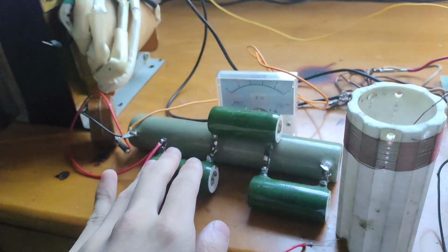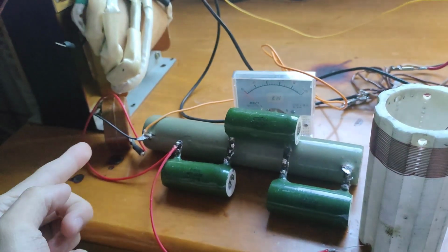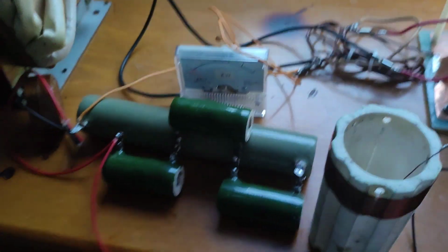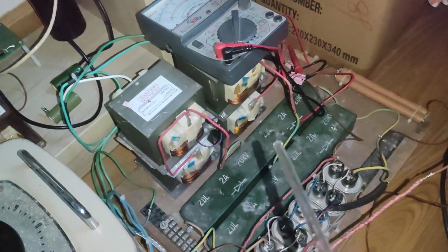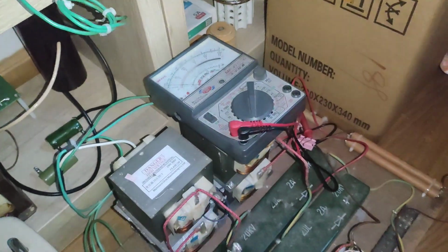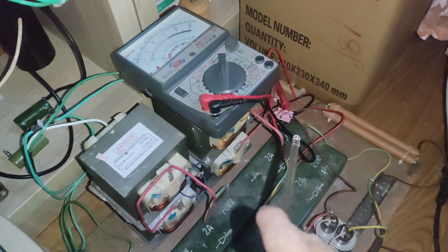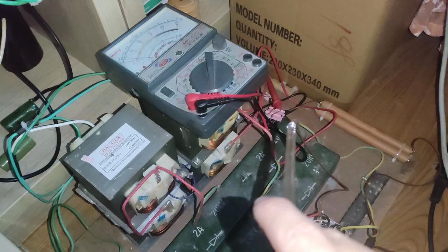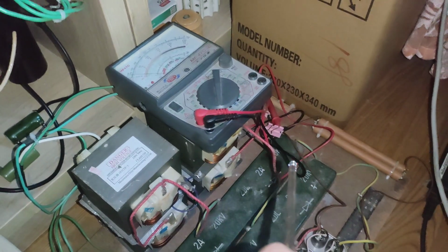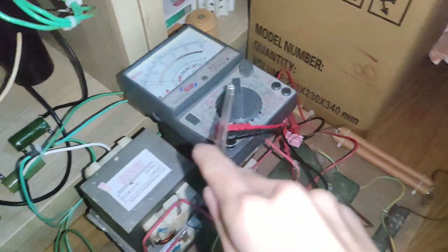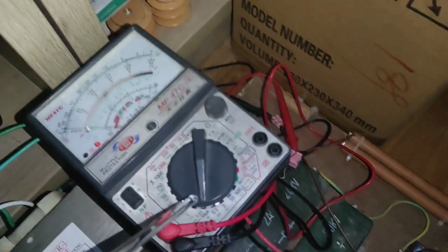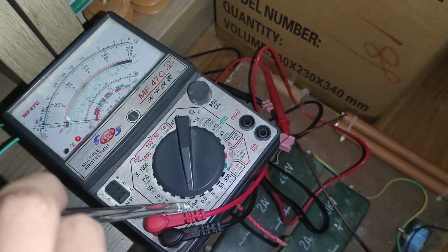4.5 kilo ohms of grid resistor, and the grid leak filtering capacitor, grid choke. Here, as you can see, is my HV power supply, and unfortunately the high voltage meter, which was originally a 50 microamp meter, was burnt due to the RF signal yesterday. So simply I'm using this multimeter, 50 microamps, this one, as you can see.